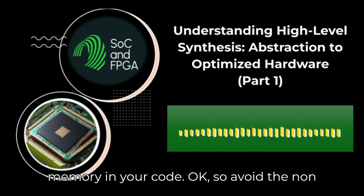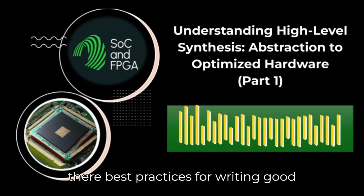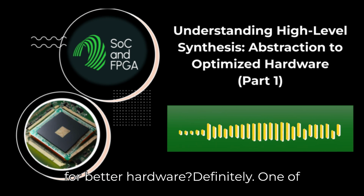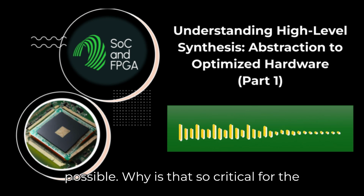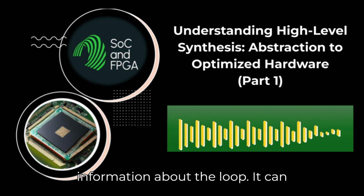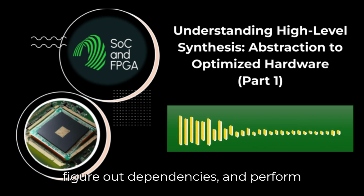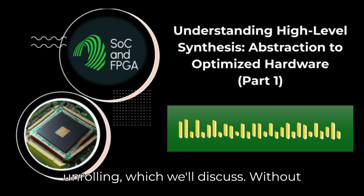Okay, so avoid the non-synthesizable stuff. But beyond that, are there best practices for writing good HLS-friendly code? Code that sets you up for better hardware. Definitely. One of the most important, as we touched on, is using fixed loop bounds whenever possible. Why is that so critical for the tool? It gives the HLS tool complete information about the loop. It can accurately calculate the loop's latency, figure out dependencies, and perform really powerful optimizations like loop unrolling, which we'll discuss.